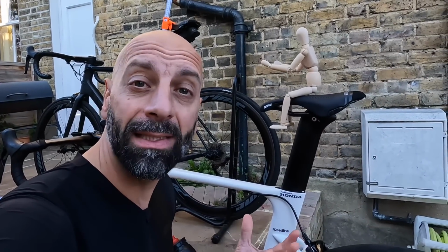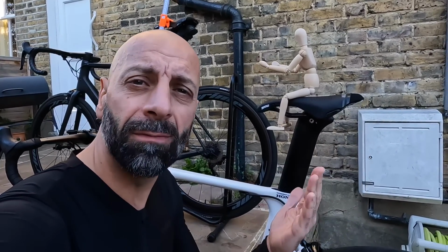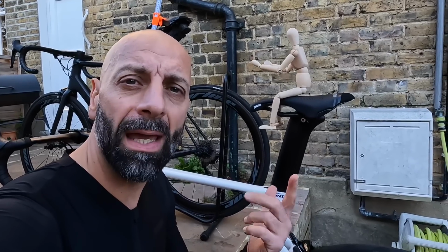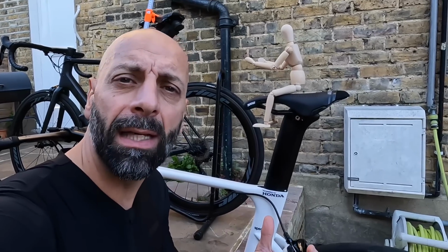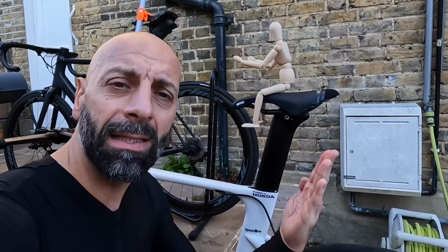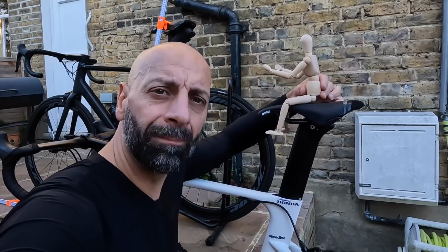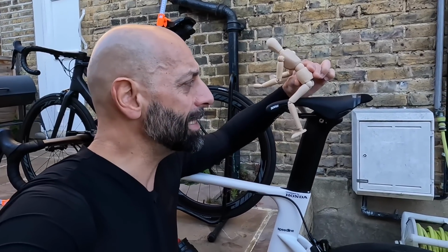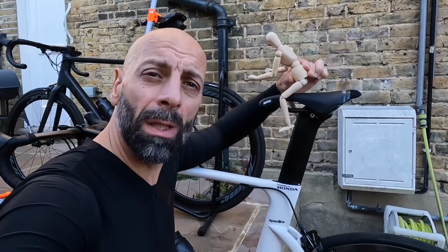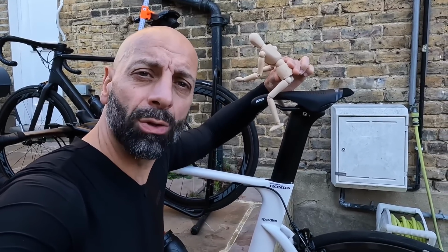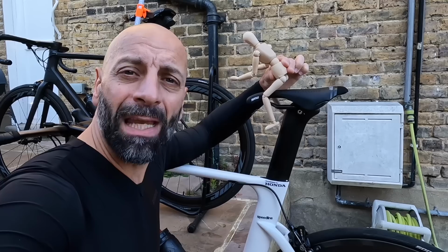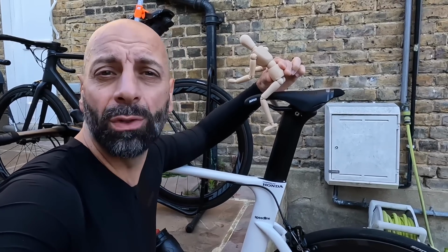As you may have seen lately, a lot of pro riders tend to push the saddle forward, usually using a bike that is actually smaller than the normal size, maybe to get the seat post even more forward towards the bottom bracket, push the saddle even further, and use a longer stem to adjust the reach. So in essence they go rotating forward, and as you can see, a smaller bike will put you forward naturally towards the bottom bracket, and again a longer reach is managed with a longer stem, like 13 or 14 centimeters.